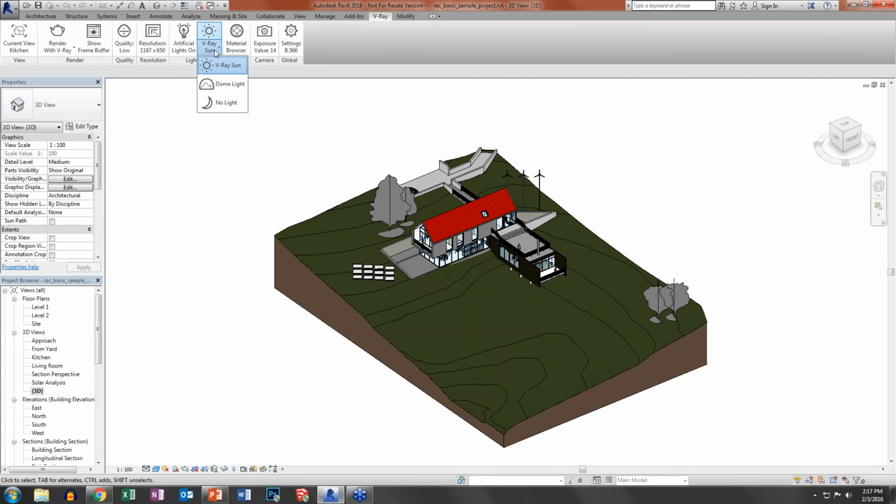Exterior lighting, we support V-Ray Sun. V-Ray Sun is actually attached to the environment mechanism built into Revit itself, again, non-destructive to the database. So if you change time of day through native Revit, that will come through without any hiccups. It'll show in the V-Ray Sun, and all we're doing there is translating the sun into a V-Ray Sun and maintaining the rest of the mechanism.